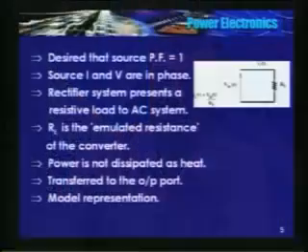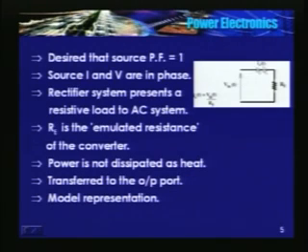So this is the equivalent circuit. The angle between V in and IS is 0. That can happen only if the load is resistive, purely resistive. Please note, we are not connecting RE at the output. In other words, power supplied by the converter is not dissipated as heat, it is just a representation, the entire converter can be modeled as if it is supplying a resistive load. Power is not dissipated, power is transferred to the output port of the converter. So RE is known as emulated resistance, or this technique is also known as resistance emulation.